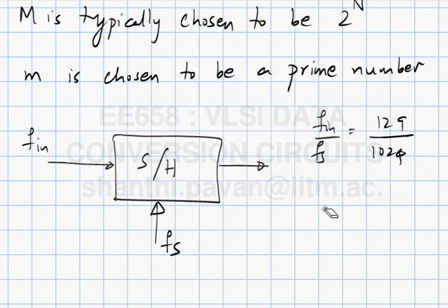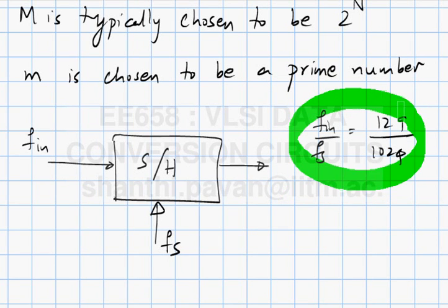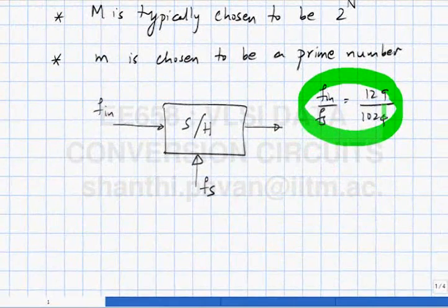So, the question being asked is, this whole setup, this frequency being some magic number times Fs, is only required while testing the sample and hold. When are we ever going to test sample and holds in the lab in isolation? It's all likely to be the front end of an A to D converter, right? So all the discussion that I had yesterday and today will hold without any change for whole A to D converters, because all that follows once you have the sample and hold is a quantizer, which is again simply taking this discrete time sequence and giving you another discrete time sequence. So the discussion that we have today with respect to the FFT, choice of input frequency, frequency bins, all this stuff holds without any change when we talk about A to D converter testing. I'm not going to talk about it at that point. I'll just gloss over it simply because I've discussed it in sufficient detail here. Does that make sense?